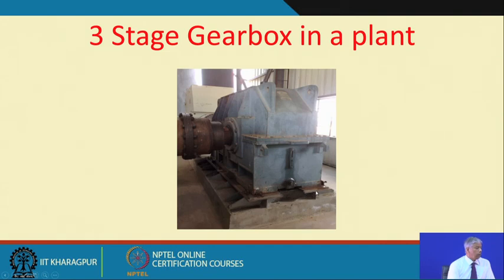You see these shims and the foundations have corroded because this was very close to a sea, this is a port, and the gearbox foundations corroded, and this gave rise to misalignment, and there is a lot of vibration in the gearbox. But coming back to my discussion on gearboxes, we can measure the vibrations near the bearings and on the foundation of the gearbox and so on.